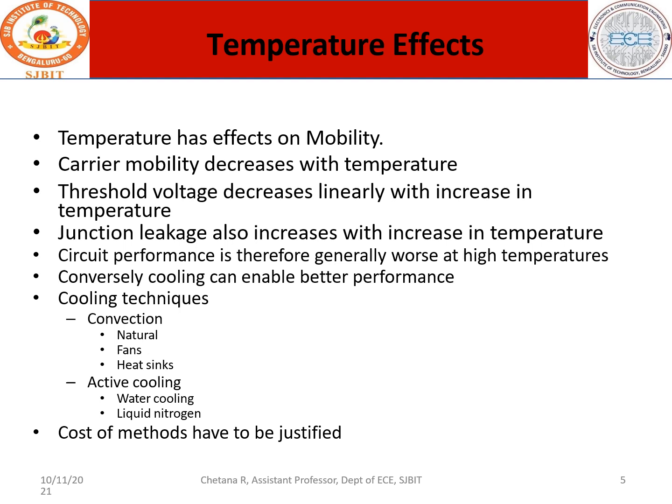So the threshold voltage, if it is supposed to be 0.2 VDD in NMOS, will reduce even before that and can be less than 0.2 VDD because of the rise in temperature. So it has an adverse effect if there is a rise in temperature.